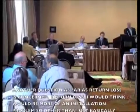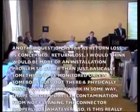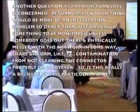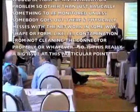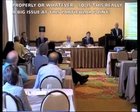Another question as far as return loss is concerned. Yep. Return loss, I would think, would be more of an installation problem, so other than just something to be monitored, unless somebody goes out there and physically messes with the network in some way, shape, or form, like contamination from not cleaning the connector properly or whatever. So, is this really a big issue? So the question is, is return loss really a big issue if you have clean connectors after the installation?